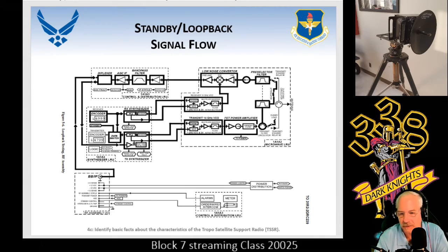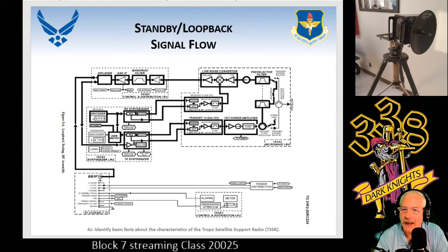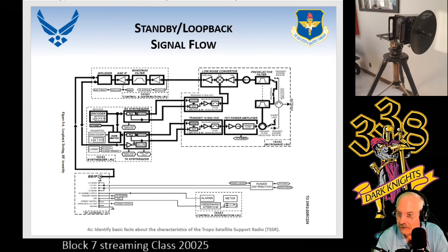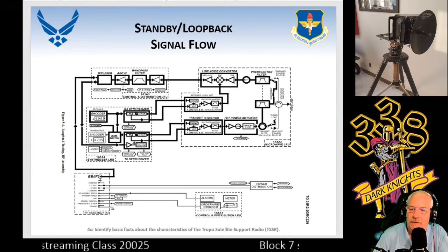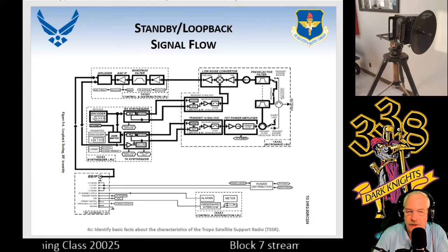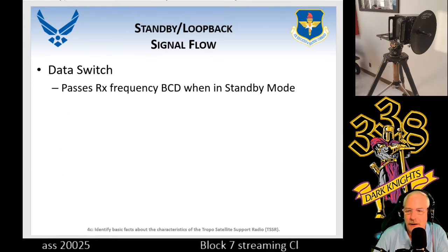That's where the test tone comes into play, and that's where you, when you speak on the handset and the headset, how you determine if your order wire is working as well as your transmit and receive section in the whole assembly. So by looping it back, you'll be able to check everything out. And that is with the standby operate switch in standby. So let's take a look at what it comes up with.